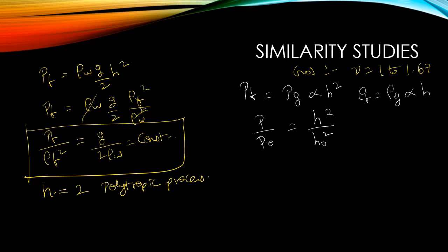During stagnation, without running the surface water, what is the depth? After running, what is the depth? So P/P0 is (H/H0) squared. This is your stagnation pressure equation measured with respect to hydraulic analogy.